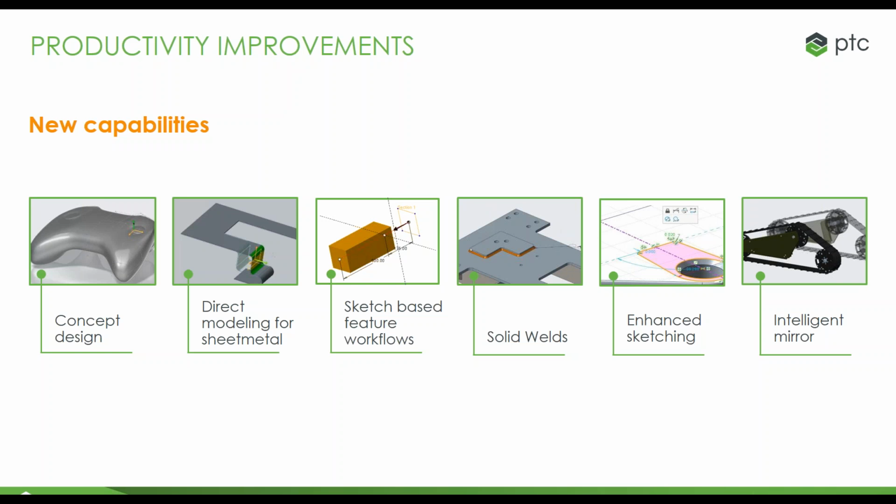There's also direct modeling for sheet metal. PTC introduced flexible modeling back in Creo 1.0, and direct modeling capabilities and workflows were fully integrated into Creo Parametric. This provides users with the power and flexibility to make late-stage design changes to parametric models, make changes to imported models, and simplify models for analysis. With Creo 4, this was expanded to handle sheet metal parts as well by understanding and maintaining the unique characteristics of sheet metal parts, such as corner reliefs, seams, and uniform material thickness.